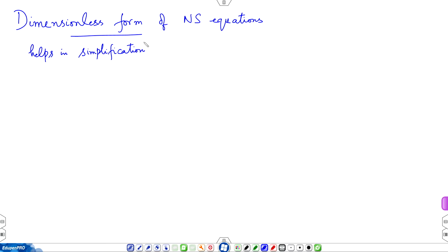Two different contexts, but the same Reynolds number will give you the same solution in dimensionless form. So, that means two different flow fields with identical Reynolds numbers will have identical solutions in dimensionless form, which is the principle of similarity. So, non-dimensionalization enforces principles of similarity.